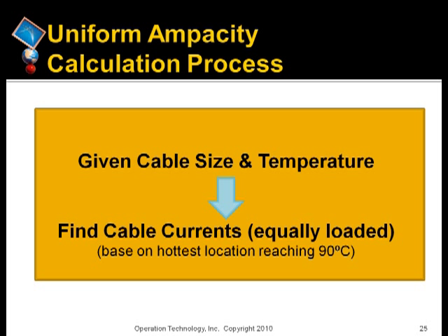ETAP will determine the initial loading level based on the base ampacity and then calculate the cable temperature in the steady state temperature calculation. Then it will check the temperature value against the cable temperature limit.